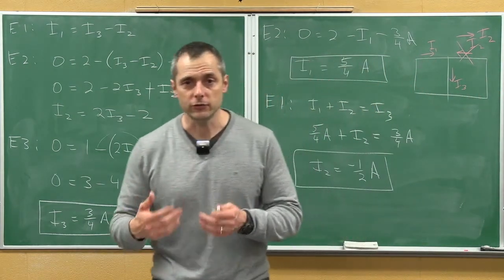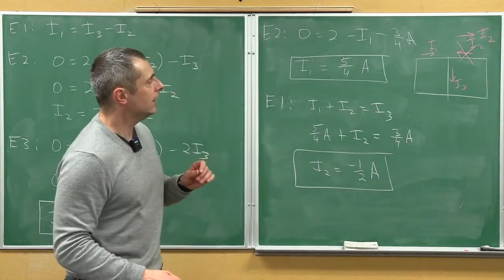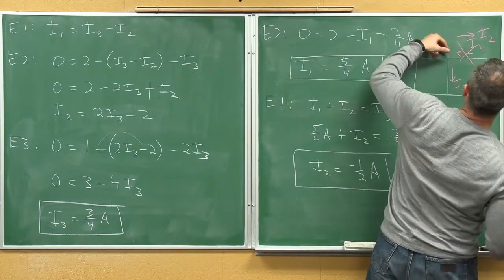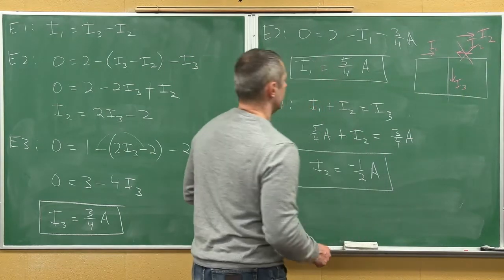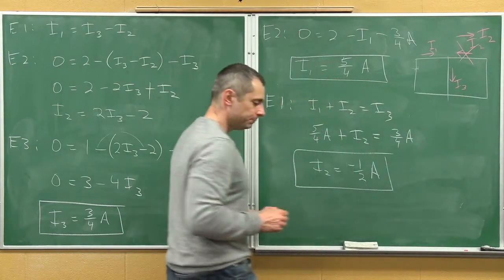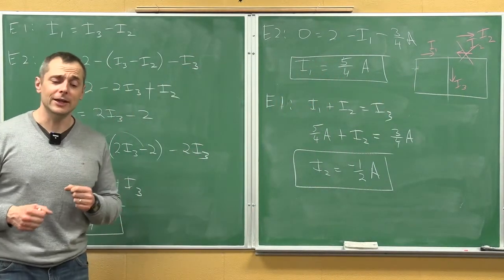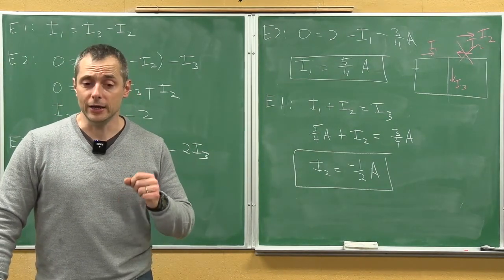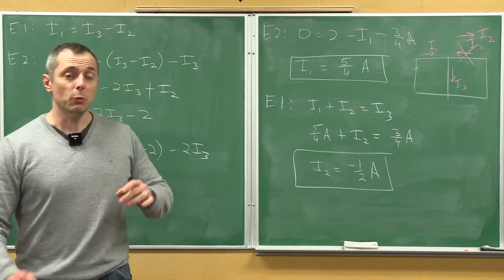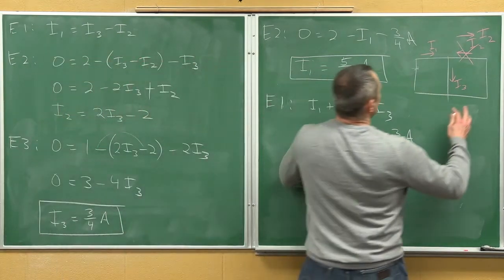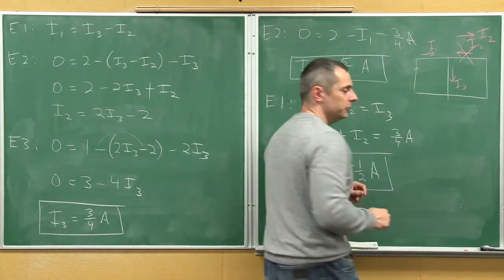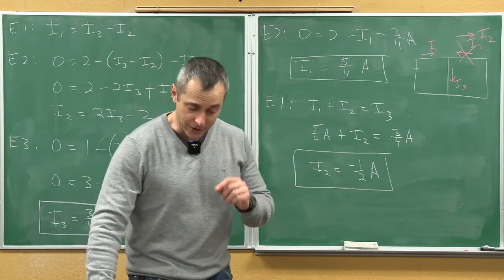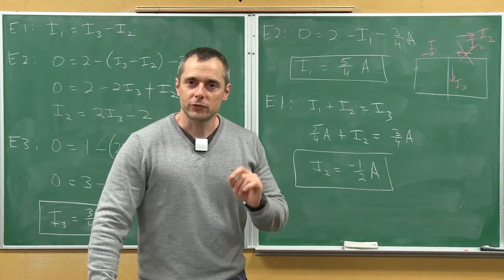So that's the nice thing about Kirchhoff's rules guessing. The current comes out of here, forces this battery to recharge, and then goes down through this resistor because of that 12 volts over here. So that was a really kind of long, tedious Kirchhoff's loop and junction rule application. When you have 2 loops like this, batteries and resistors in 2 loops, you always get a system of equations in the problem. All right, but that was Kirchhoff's rules.